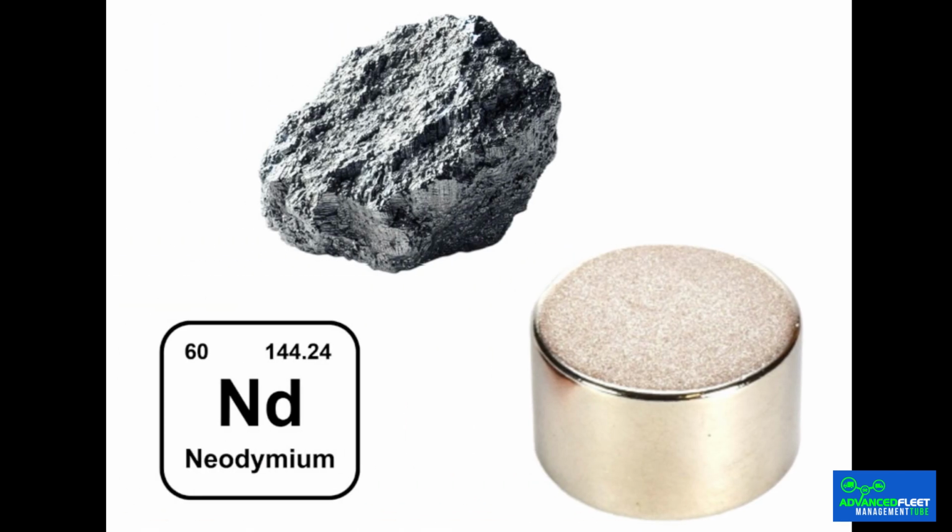Regarding synchronous motors, it is important to note that they use neodymium-based permanent magnets. This compound was developed in 1983. Since then, this compound of neodymium, iron, and boron has become the standard for quality magnets due to its high magnetic field concentration. The arrival of this material has revolutionized the field of electric motors. With these highly concentrated magnets, two main approaches have been explored: reducing size while maintaining power, or maintaining a similar size while increasing power.